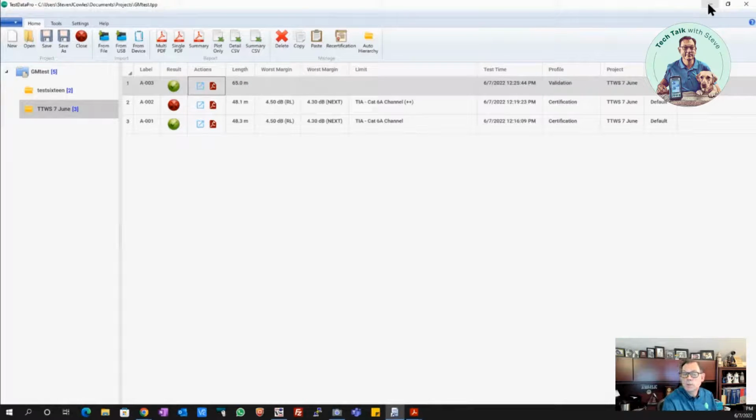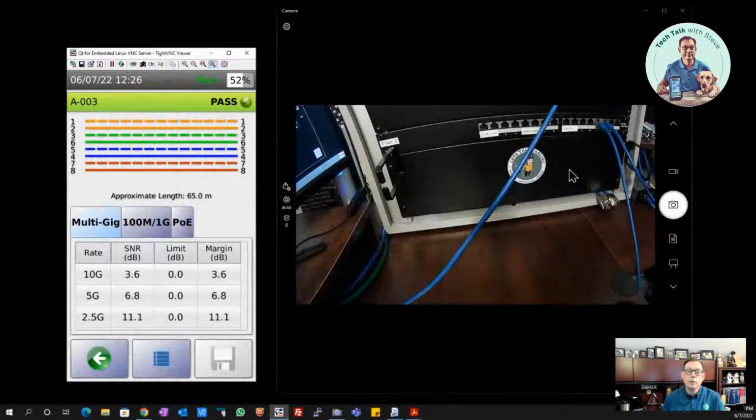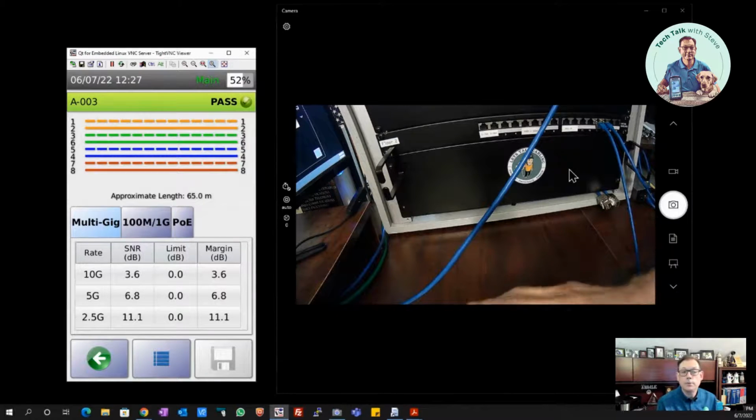So again, these are things that we would want to look at when we're considering assuring that infrastructure readiness for our smart building systems. So, we're looking at, again, all these different devices that are running over PoE. DC resistance unbalance is a very important test for this when you install the cabling. But beyond that, you also need to be able to do some additional things. And being able to have all this built into one tester rather than having to go back and forth between multiple pieces of equipment is pretty convenient. So that helps to be able to take your certifier and actually just plug an additional test adapter module into it and run these tests.